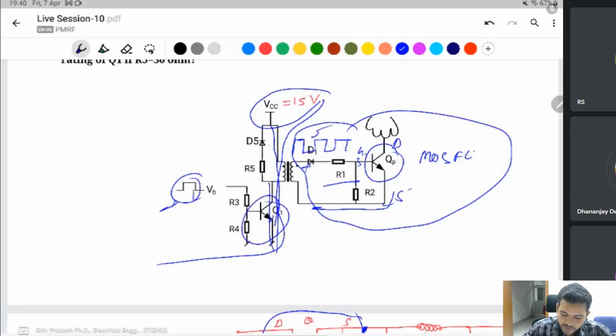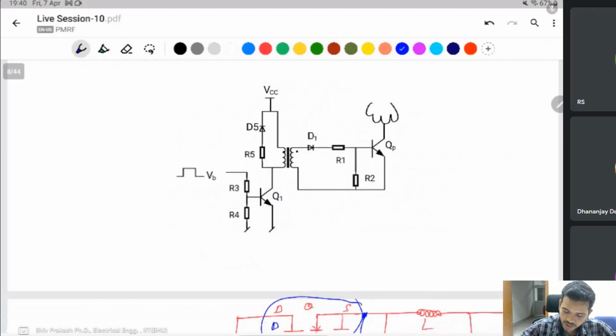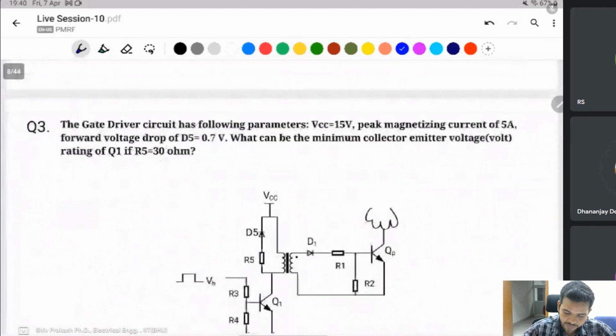This one off means the remaining circuit discharges through the diode and the resistor. And this one is 0, and this switch is off. This type of circuit is required for the floating MOSFET or upper side MOSFET, upper side switches as they are known.